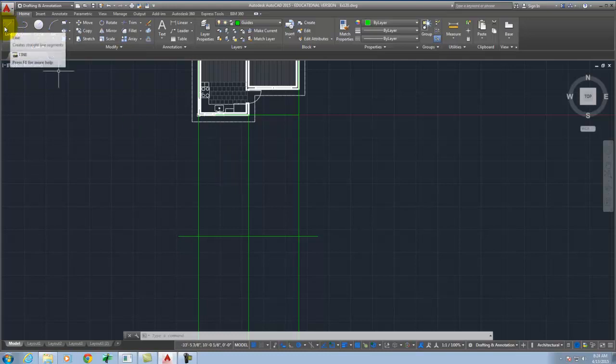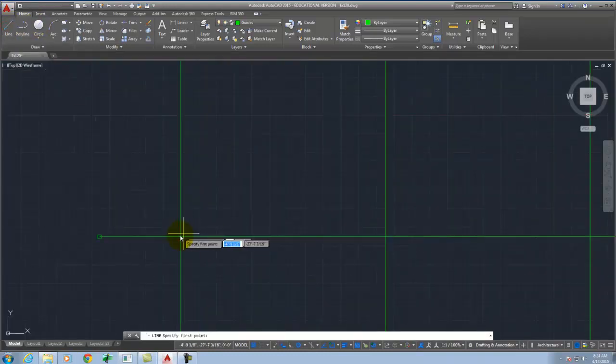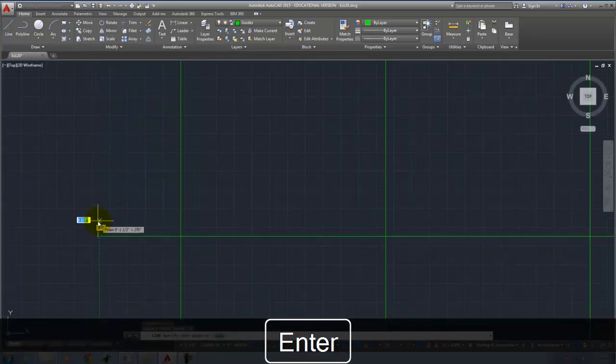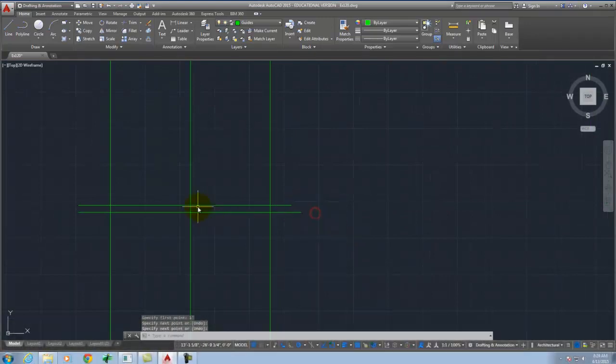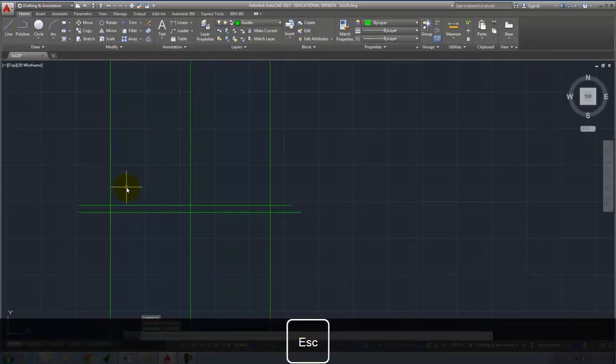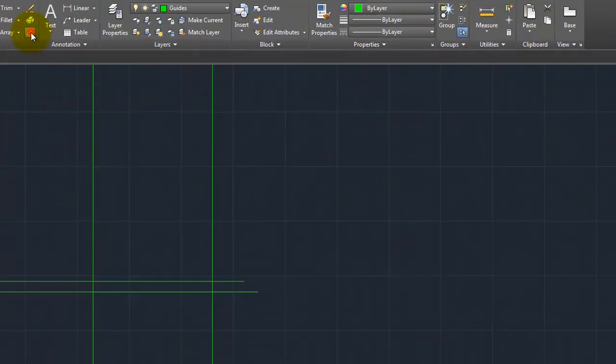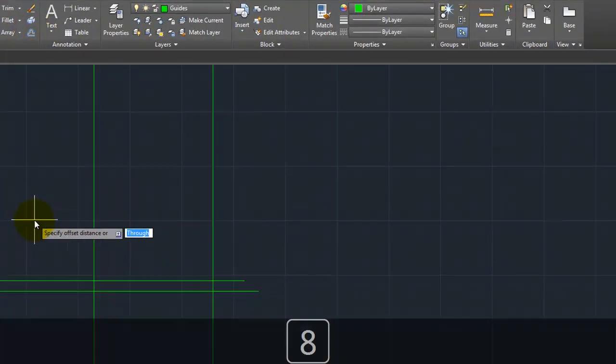So first thing I'm going to do is start here and go up a little bit. And we'll say a foot to be arbitrary. Right? And I'll draw another line that goes across. There it is. So that'll be my finished floor inside. Anybody know the height of a ceiling inside? Standard? 8 feet? Good. So you guys are knowing a few things, right? So what can I do? I can use the offset command. Remember, it's right here as a button. And I can say I want to offset by 8 feet.